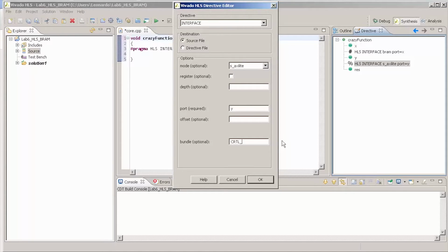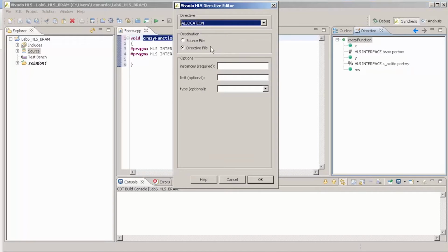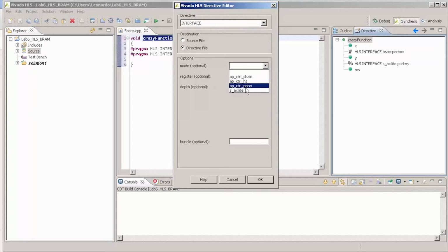Just using the BRAM itself does not mean that the BRAM will be available for you on the Zynq. We're going to use an IP core that maps the BRAM to the memory address space of your ARM inside the Zynq CPU, or the Microblaze, it does not matter.